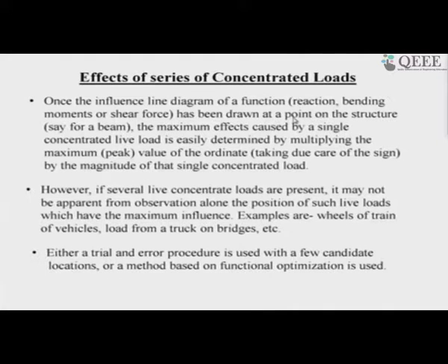So, if the influence line diagram is to be used efficiently for practical structures, where it will be very complicated in geometry and loading, we must devise methodologies to cater to an increased number of loads and also to cater to the uniformly distributed load which is sitting on the structure, spanning over the entire structure or part of it. Those things need to be conceived now. So, suppose we have multiple loading.